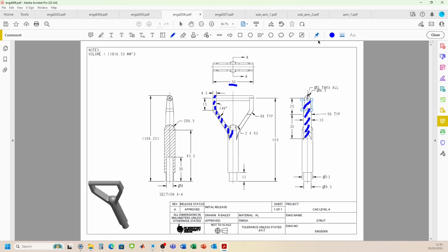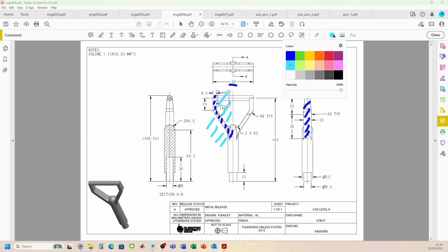And then we need to use some other extrusions in order to remove these shapes here. So we're going to have to remove this section here, this section here, in order to get the blue outline of that shape. We'll use an extrusion, then we use some extrusion cuts to remove that material. You might be saying, how come you're not removing the material here? Well, that's going to have to be a secondary process, because it's circular, we won't be able to use an extrusion to cut that through. So we'll have to add that back on once we've removed it. So that would be another step that needs to be undertaken.